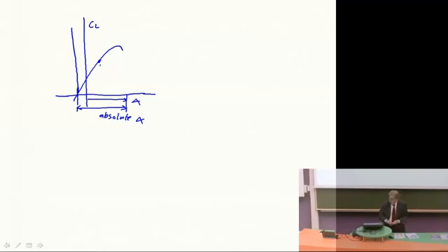One other thing I got some questions about is the aerodynamic center and the moment in the aerodynamic center. On the one hand, we have a force, which we give a certain arm, and then it matters what the reference point is, while the moment around the aerodynamic center, we just move to the center of gravity as if it doesn't matter. This confused some of you.